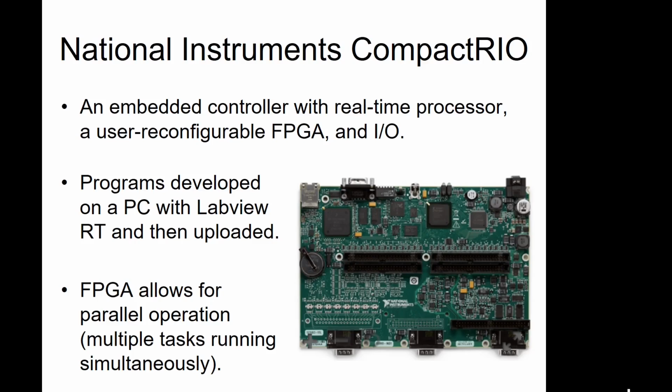But the power in this is that, because of these switches, the program's not running sequentially. When you have an Arduino, you run one line of code and then the next line, etc. So each line of code in an Arduino is run one at a time. In an FPGA, these can potentially all run simultaneously. So you have true multitasking capability here, which means they are very fast.